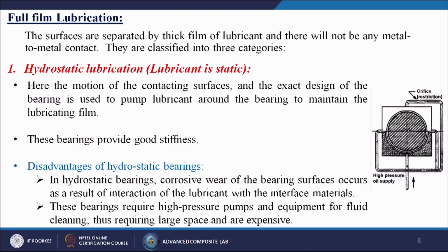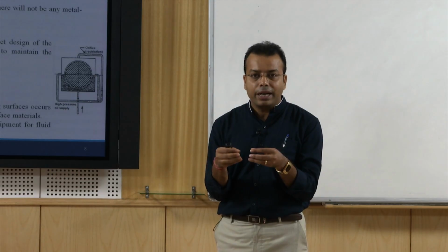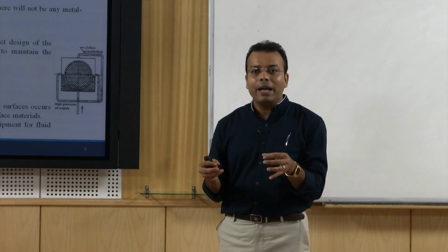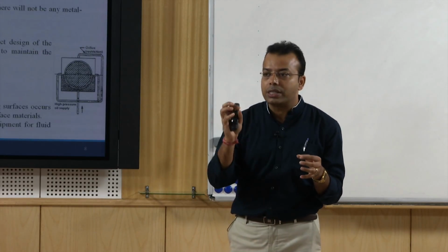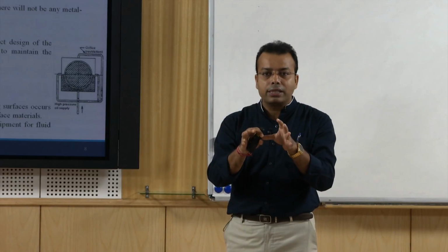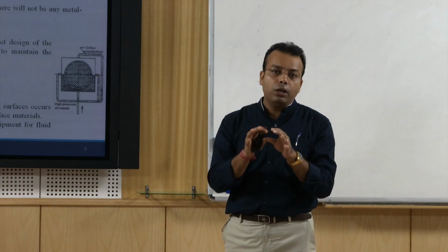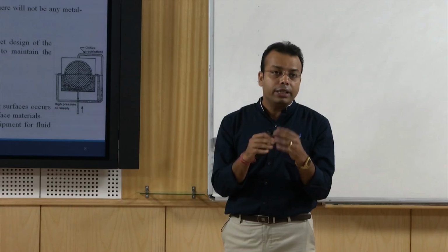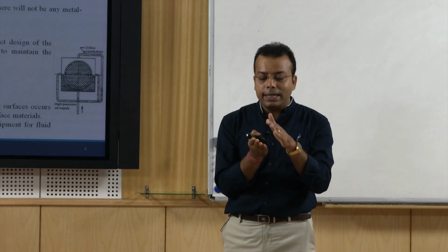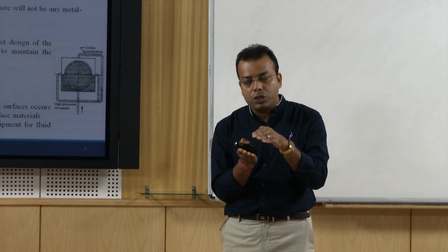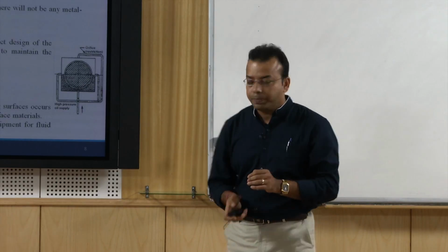So, from this particular figure you can understand that from outside we are creating certain kinds of channels, or maybe a certain kind of piping arrangement, by which the lubrication is constantly coming and going inside the system. Here the lubrication is actually not in the moving contact, only in the touching contact in between the pistons and the housing.